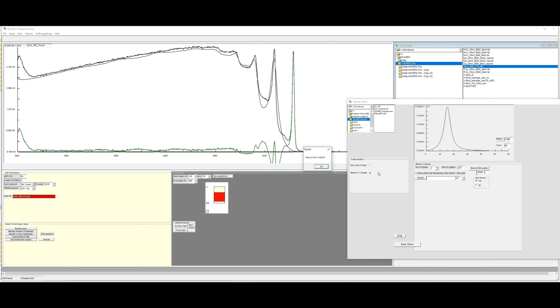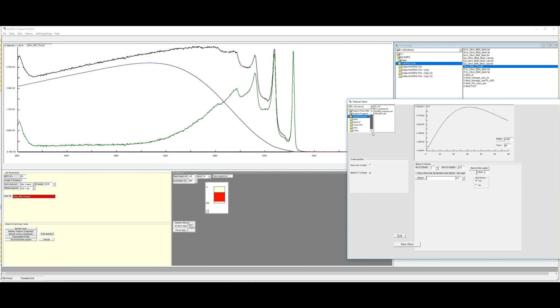You click blend of cross sections, and then we click OK here, and then we find the cross section. In the list of cross sections, we have the different cross sections here. This is the standard aluminum, germanium. The metal oxide here is the universal cross section, 2-parameter universal cross section. We have for the polymers and the silicon dioxide. We also have a cross section here that I've stored valid for titanium that we determined